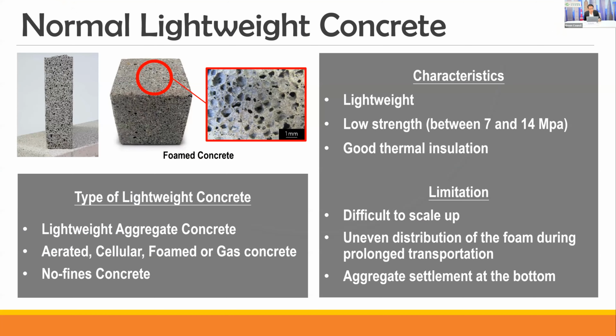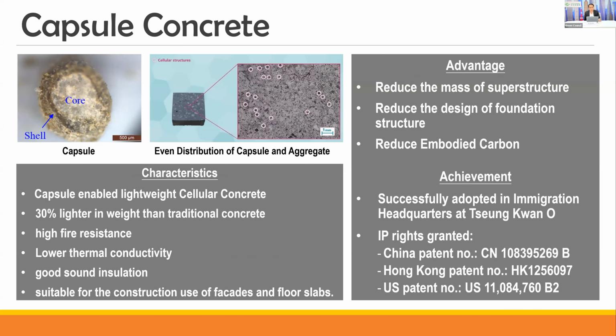First, I would like to introduce what normal lightweight concrete is. The strength of lightweight concrete is normally relatively low, so it cannot be used as structural concrete. But the new product, Capsule Concrete, is 30% lighter than normal concrete, and it can reduce the mass of the superstructure. As a result, the design of the foundation can be reduced too. Eventually, the embodied carbon of the total structure can be reduced.